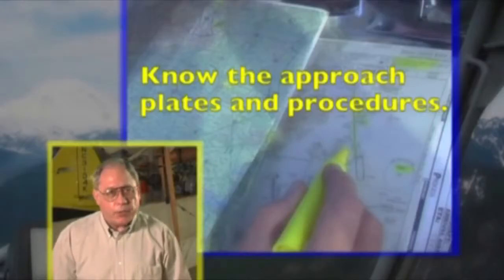The new SOP is to utilize whichever pre-flight forms work for you mentally. Go through the flight and fill out all the important information. Study and brief both the departure and the arrival. Make sure your co-pilot, if there is one, understands what you're planning. Know the approach plates and the procedures.